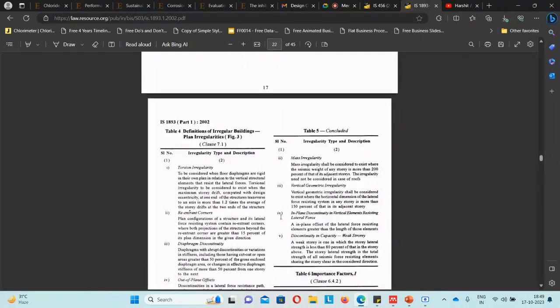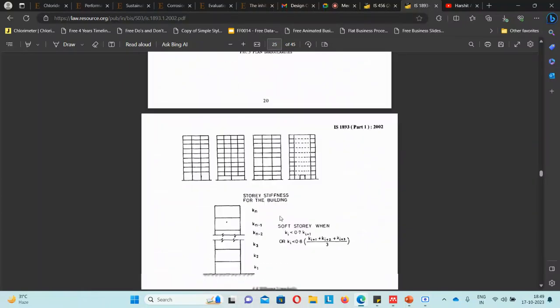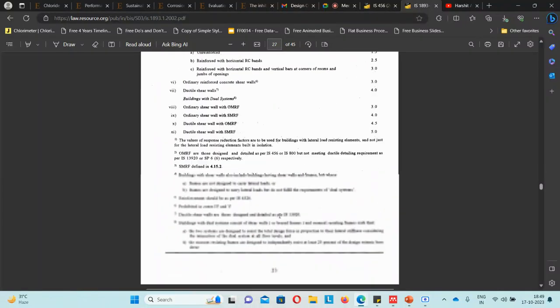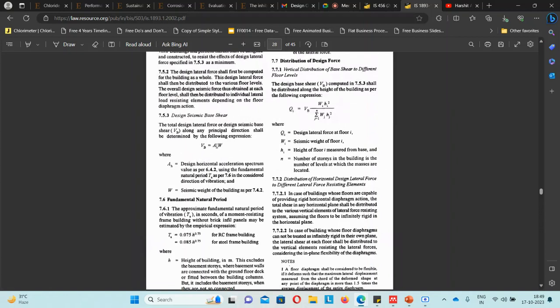And once you know the horizontal acceleration which can occur in the structure, you calculate the base shear. So Ah you calculate based on the zone in which you belong. The net weight of the building we know, as we calculated the dead load and live load for each floor; summing for all the floors, we get the net load acting on the building. Multiplying both, we calculate the base shear, or the shear that will be generated when seismic activity arises in that zone.